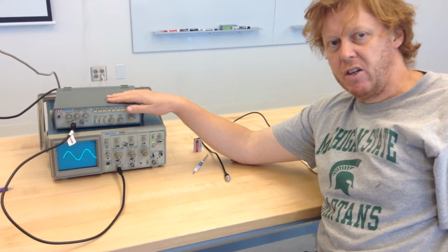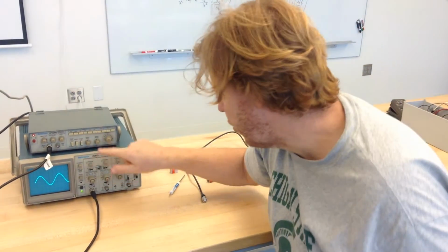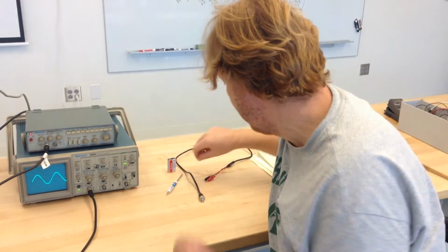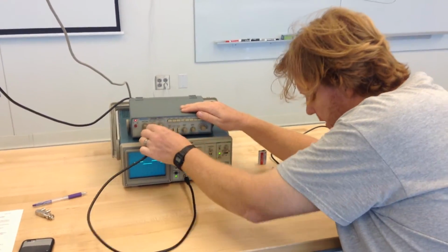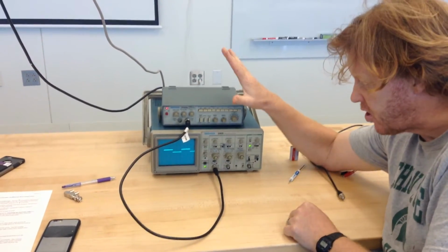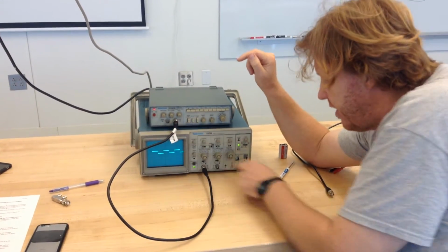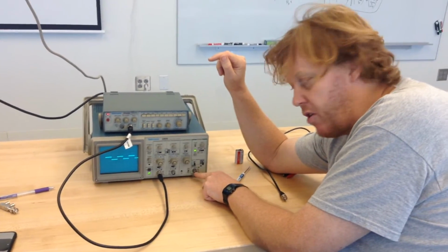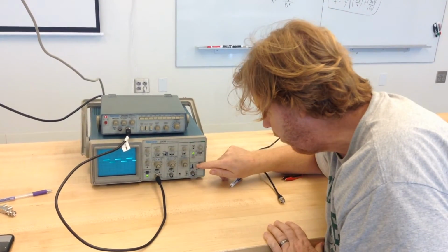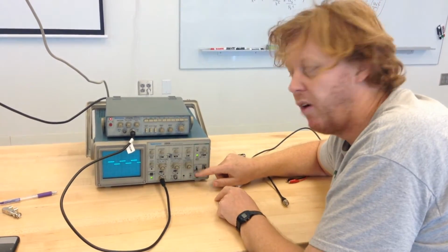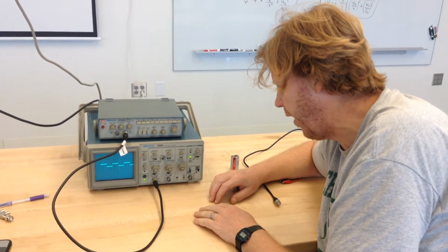So that's called triggering. Signal generators come with their own trigger signal that you can look at. So we have a 1 kilohertz sine wave signal. Well, actually, this guy here has an internal clock that makes a square wave of the appropriate frequency. And this is very handy because I can put this into this junction here in the oscilloscope and tell the oscilloscope, don't trigger off whatever I put in channel 1. That's what I'm doing now. The source is channel 1. I can say trigger off the external source if I put it in here. You often have to do that, but that's for later.